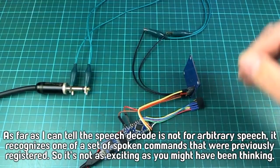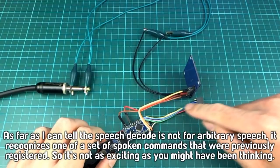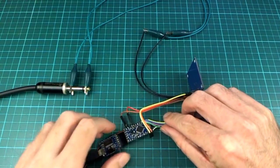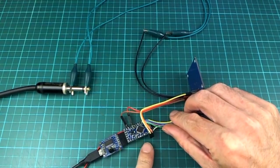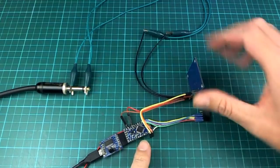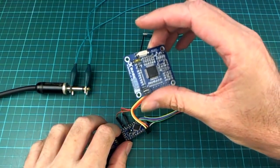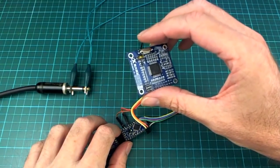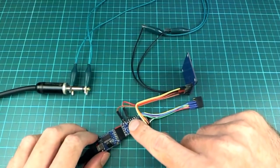So let's just have a quick look at the connections that I've got here. These wires here are unrelated. I'm just reusing this Arduino that I had. This is a 3.3 volt Arduino, by the way. I'm pretty sure you're going to have to use 3.3 volt signals for this, because this thing here is all running at 3.3 volts, and I couldn't see any documentation that said it was 5 volt tolerant on the signal pins. So just to be safe, I would recommend trying 3.3 volts only.